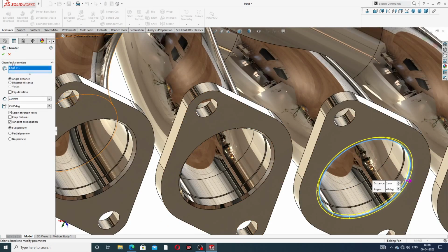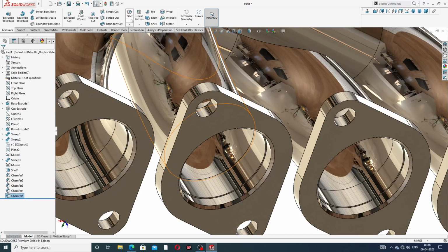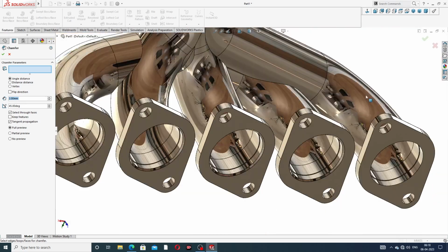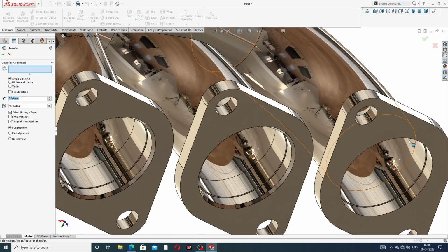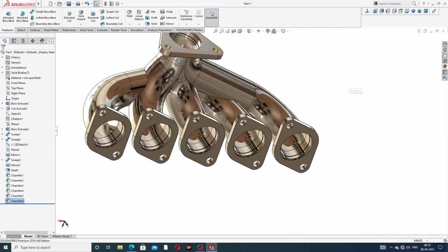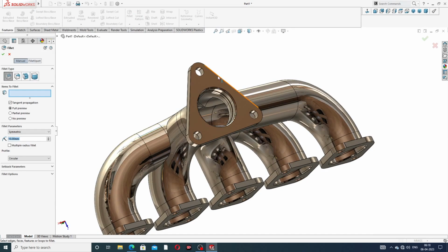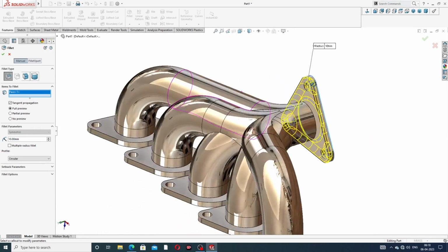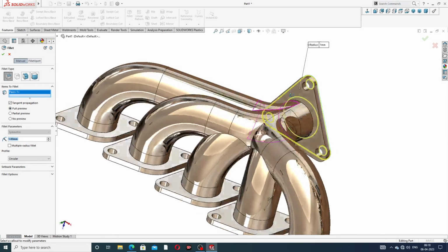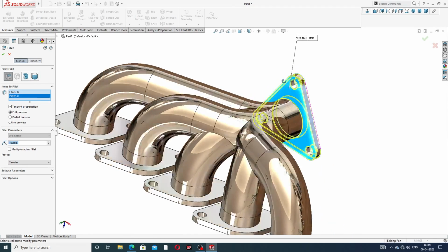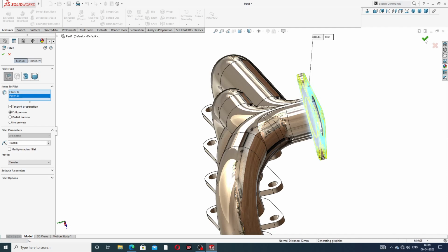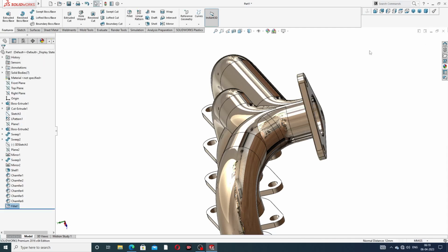And also select this. Okay, and the last one, click this. This is a 2 millimeter 45-degree angle, select here and click OK. Next, the 1 millimeter fillet is used here, select this face and use 1 millimeter, and select the back side also, OK.